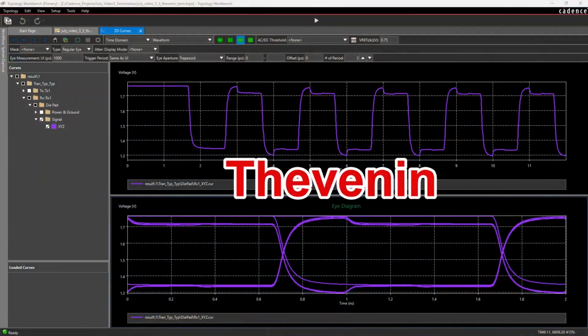So this DC termination strategy is useful for voltage biasing. However, the cost is 2 resistors per net, more power consumption, and a bigger bill of materials. So that's strategy number 4. The next 3 termination strategies are the ones you'll be going for the most often.